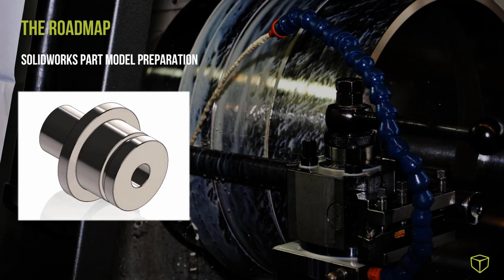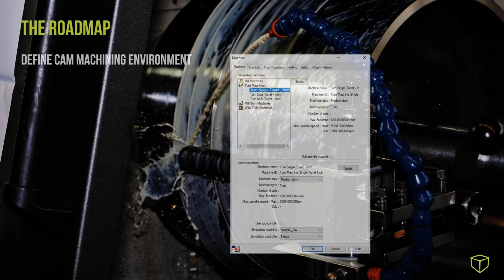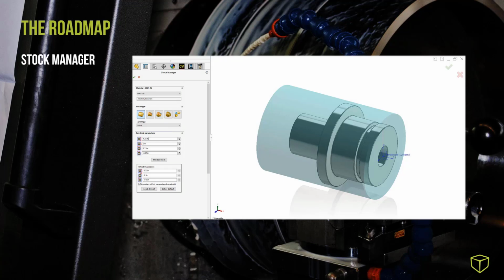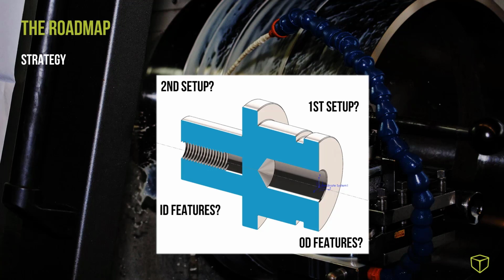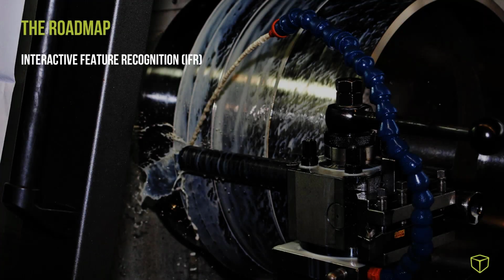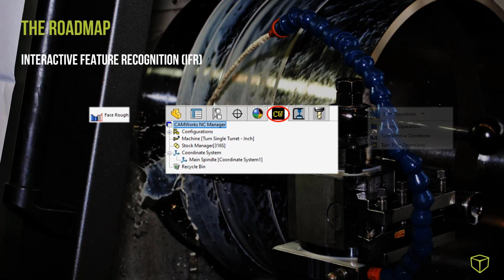Using a SOLIDWORKS reference feature to prepare the part so that it complements the CAM-specific machine environment. Define the stock, which is the material type, size, and shape from which the part will be machined. Review how we are going to program this part and think about what features, internal and external, are appropriate for each setup. Then create applicable turn setups using interactive feature recognition.